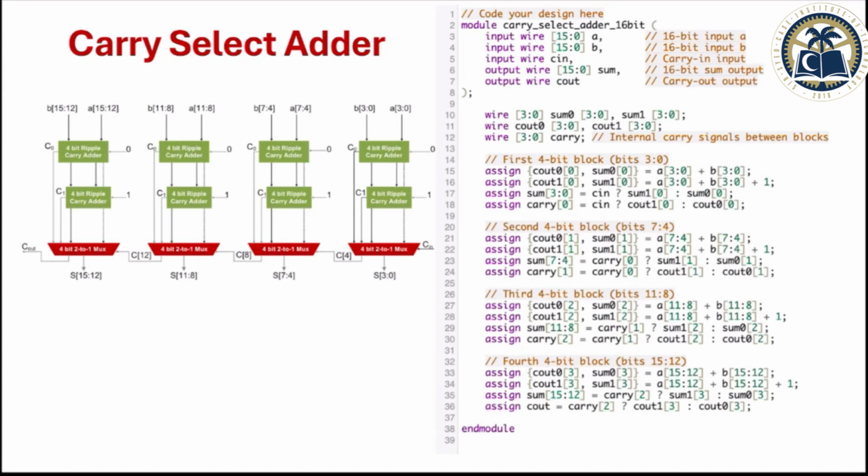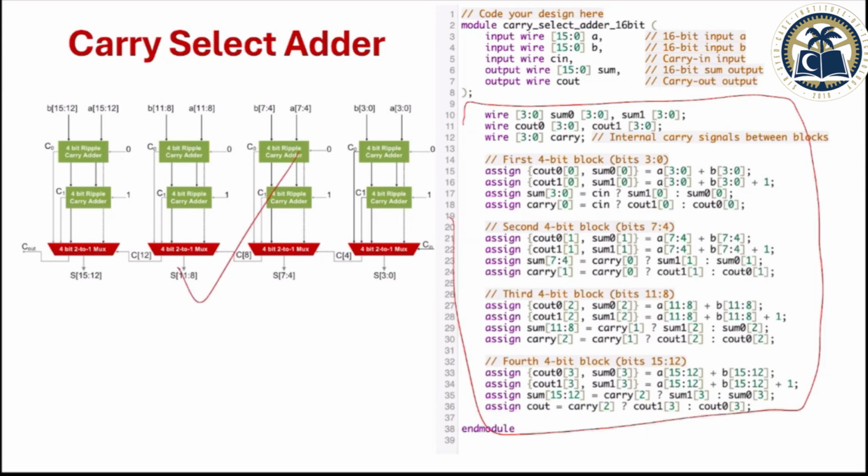So we checked adders, and we said there are some embedded adders in FPGAs, like in Versal, where you have the DSP58. Then we said you can just ask the generative tool how many different adders you can have. It will give you a list of adders, and you say, okay, generate me, for example, a carry select adder.